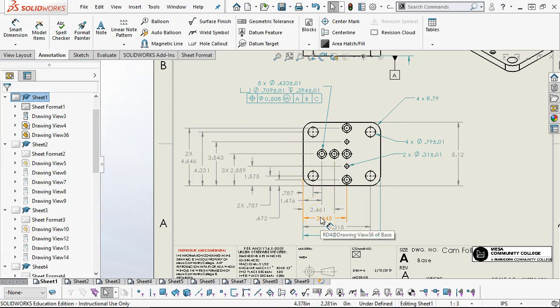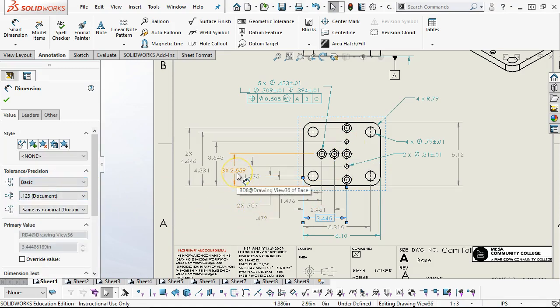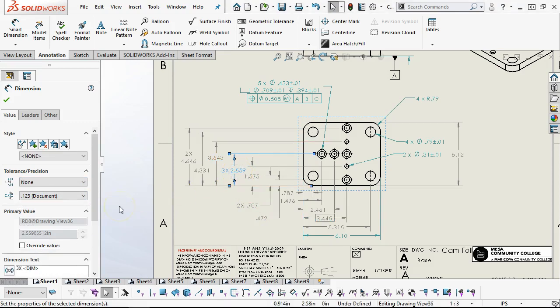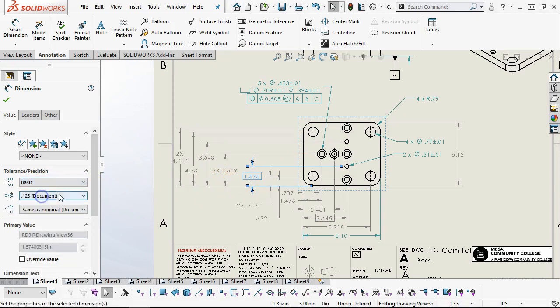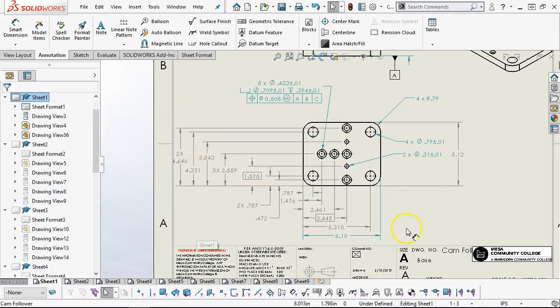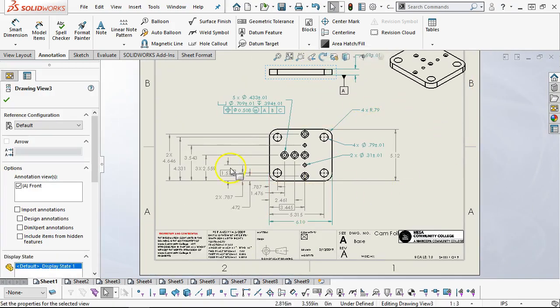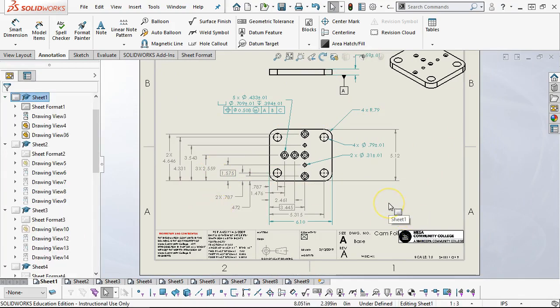So as I identify those items, I don't think the counterbores are really the critical. The pins are the critical items. So as we start thinking about our tolerancing, those are going to become the dimensions that pick up the basic. All right, so the 1.575, that gets a basic, the 3.4543, and that gets the basic dimensions. All right, so it's stretched out on me a little bit more, and we'll bring that in.